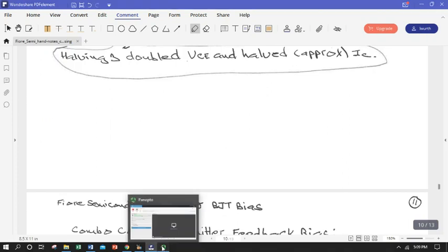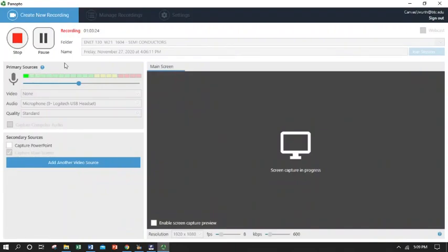So that is it for biasing schemes. Big takeaways. Why do we bias? Because someday we are going to put an AC signal in our base and we want it to completely go through and be amplified, and be able to take an amplified signal out at the collector or emitter. We don't want it to all get cut off just trying to overcome the forward voltage of the PN junction, the base emitter forward voltage bias.